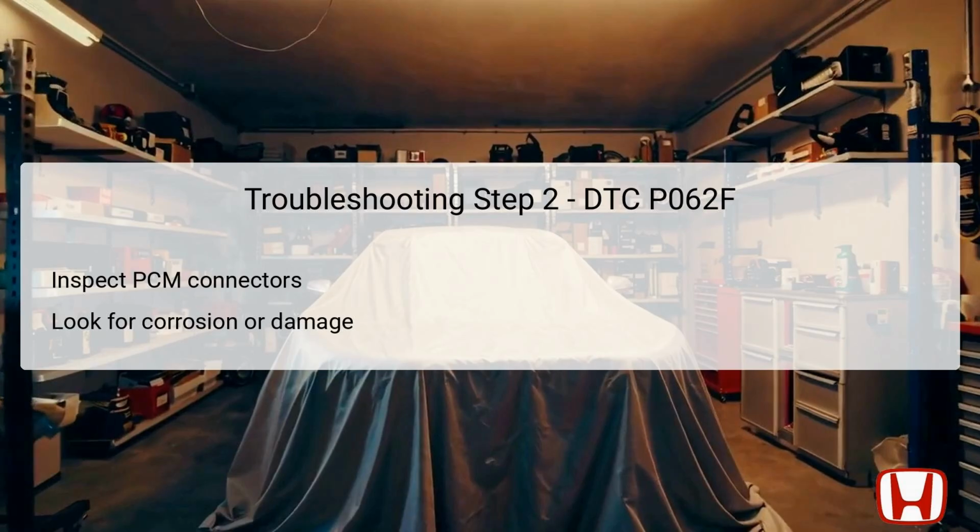Cleaning or replacing damaged connectors is essential to ensure optimal conductivity and restore communication pathways. Additionally, verify that the wiring harness connected to the PCM is intact and not frayed. Addressing these potential issues can often resolve communication problems between the PCM and other components.